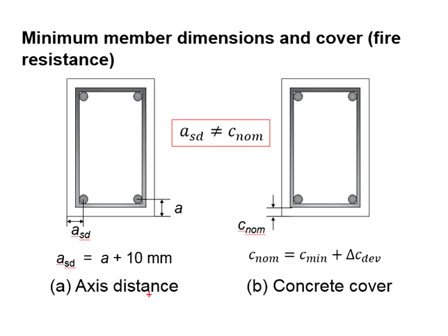Otherwise, the axis distance shall govern. Therefore, in the actual calculation, you will need to calculate both. As their dimensions and their reference point vary slightly, you will need to do some simple conversion, converting the axis distance to the equivalent thickness of the cover.